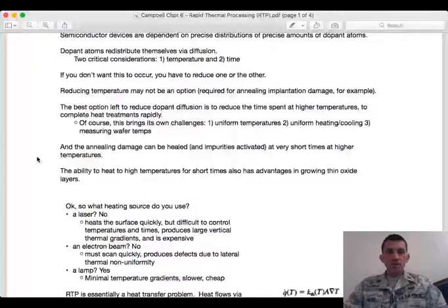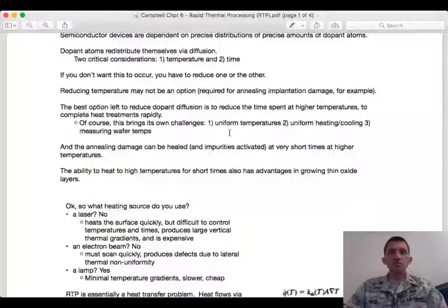If we can make 1,000 at a shot, then it's going to cost 1,000th of the price, but that means that you want to have the same device quality coming out of a location, say near the center of the wafer, the silicon substrate, and from the edge, right? So if you're going to do this rapid thermal processing, you need to make sure that your temperatures are uniform across the surface so you get the same result all across your wafer.